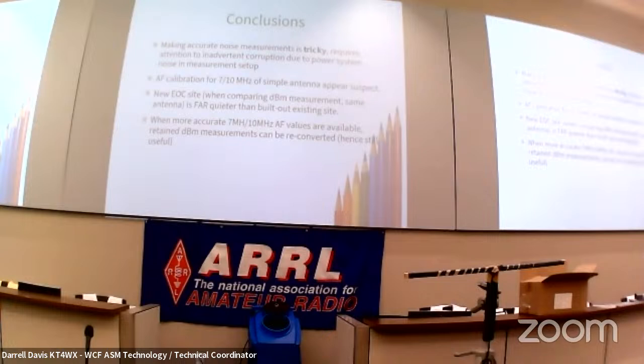It's those diodes and the switching that go on and off and on and off, sucking power real fast to charge up that capacitor. That's where the RF gets generated. And then your whole house wiring is the antenna. Same problem if you've got a solar panel system. Your charge controller is making huge amounts of noise. And the same solutions for your charge controller solve this problem.